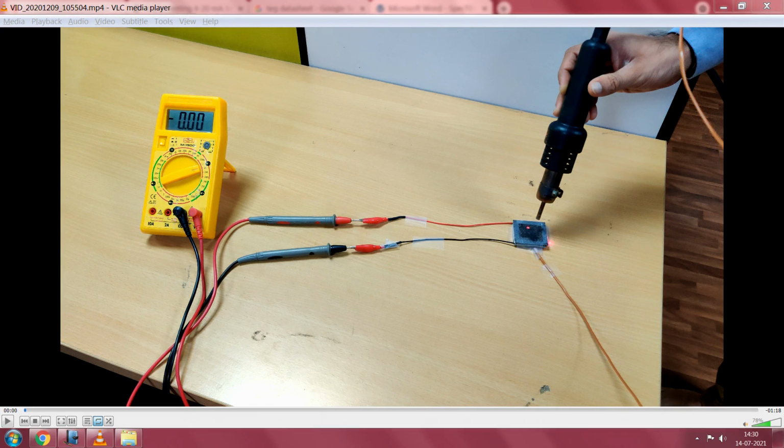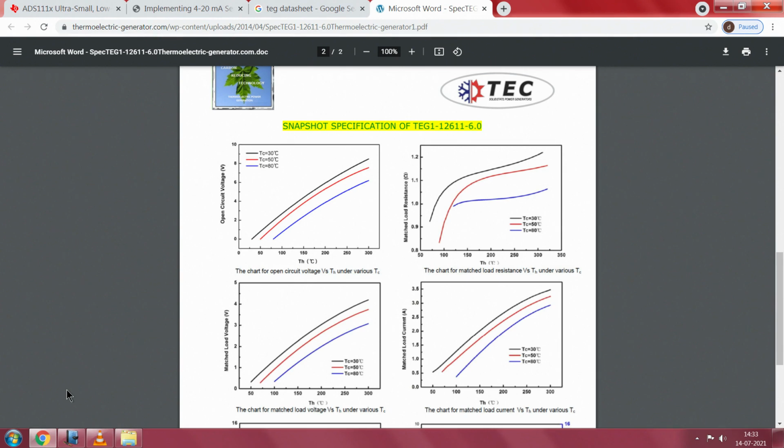So, let us see what temperature differential you will get, and for that temperature differential, what the output voltage should be. That you should also know. Then you will be able to go back and say more or less my way of measurement is okay, and that I am able to control the losses quite well, and as per the data sheet I am getting some number.